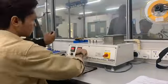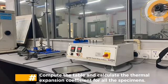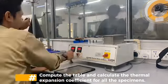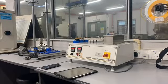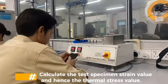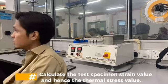While waiting for the experiment, we can compute the table given in the lab manual and then calculate the thermal expansion coefficient for all the specimens. And then, we need to compare the readings with the theoretical readings. After that, we can calculate the test specimen strain value and hence the thermal stress value.